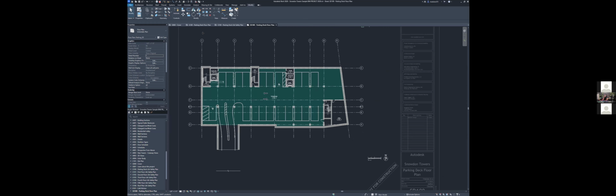Alright. So as mentioned before, one of the main differences between the model line and the detail lines is that the model line shows across the different working drawings. So I have three different drawings here. It's three versions of this same parking drawing board. One is for showing the parking lot, one is showing the safety feature of the parking, and one is showing the regular floor plan of the parking lot. In this case, the detail line was used as a turning radius on the regular floor plan. As you can see, that line is not shown across these two drawings.